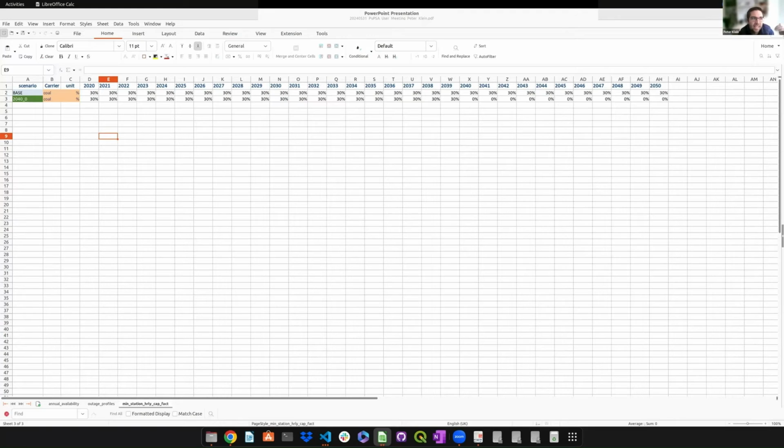Basically, any generator in the fleet, and remember we're talking multiple units combined, we don't let that ever go below, say, 30%. Once you get to a more detailed unit commitment, then obviously you can get to min stable level, and whether a unit switches off or not, that's a bit more detailed.